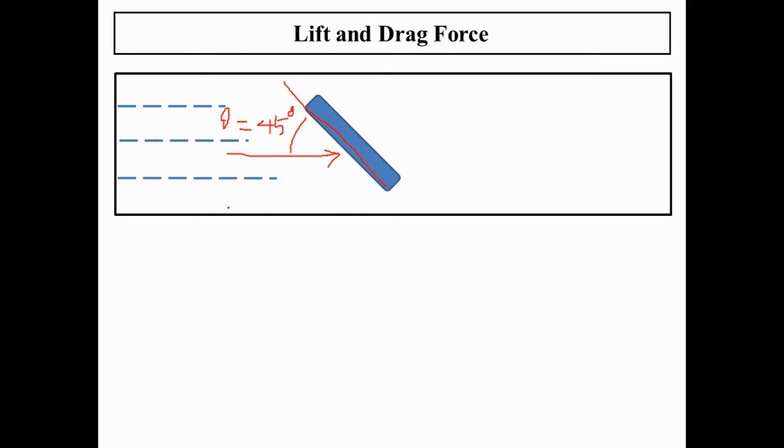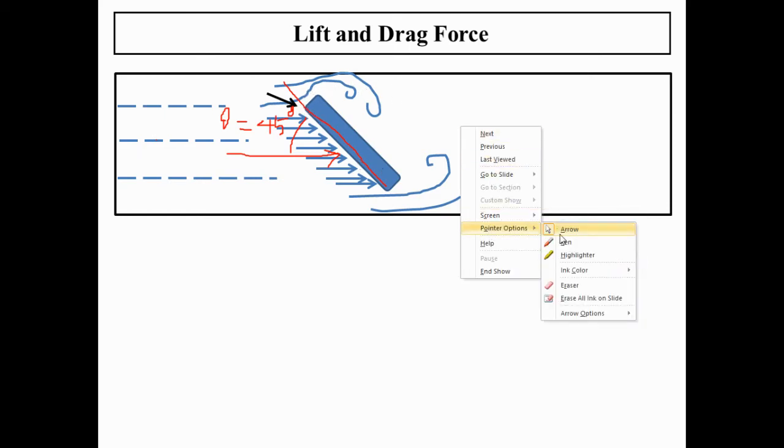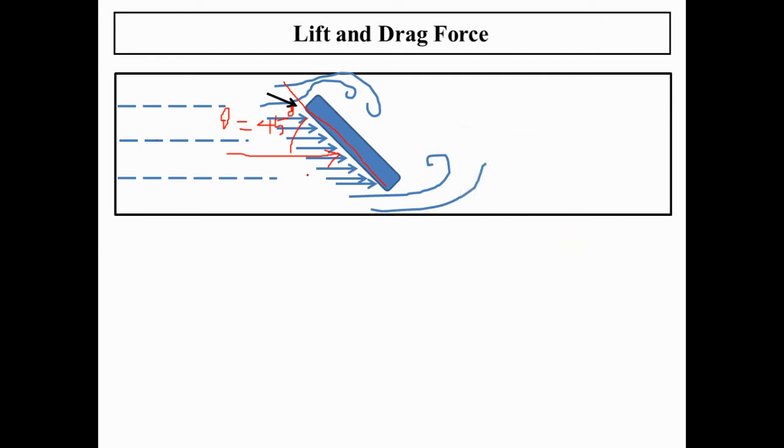What would happen when the flow is coming? You can see that a lot of the streamline flow is being captured by the object, and the flow gets separated from here. You get a high pressure region, because a lot of force is acting on this surface, which means the kinetic energy is converted, the velocity drops to zero, and more pressure energy is acting here.